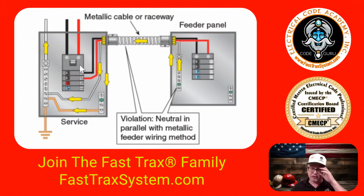All right, so let's look at this right here. This is the illustration that we posed. So here's your main breaker, here's your feeder breaker, and this is a feeder, and it's coming down into this remote distribution panel, this feeder load center, however you flavor it. The one thing you'll notice is that it only ran 3 conductors. And so here the neutral has a green screw and it's bonding it to the enclosure. This is where we're talking about an improper case to neutral connection downstream of the service equipment.